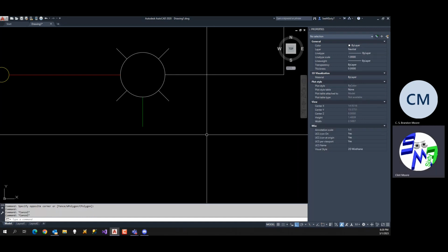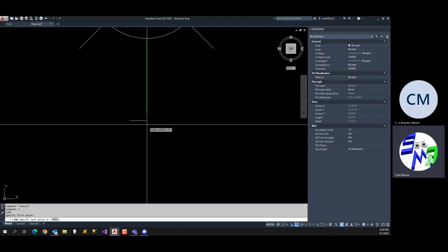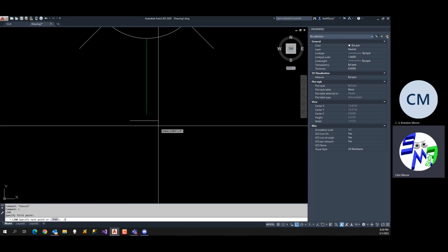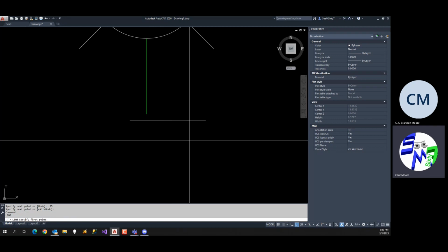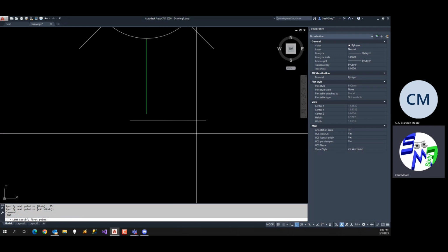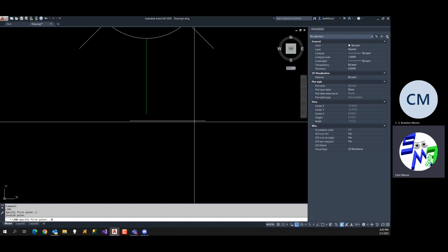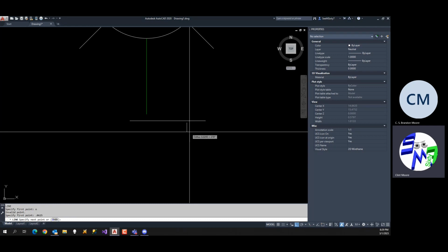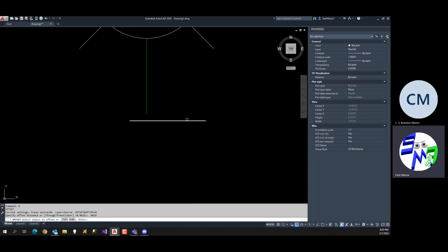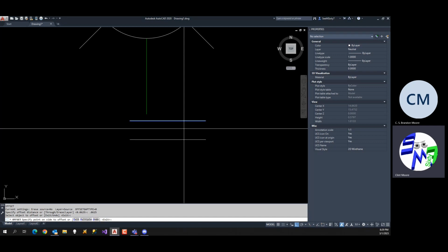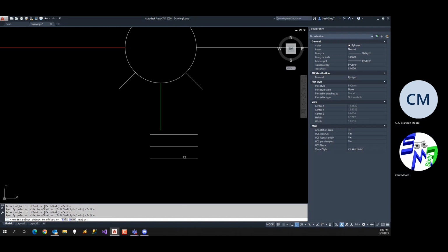All right. Now, another symbol in the electrical library is a ground symbol. I'm going to draw a ground symbol for us. I'm going to draw from here. I'm going to draw this over, let's say 0.25. Boom. And then I'm going to offset this. Offset. And we're going to say 0.0625. Oops, that's on the line command, my bad. Offset 0.0625. All right. Again, that's a 16th of an inch. All right, and we might be able to squeeze more in there.